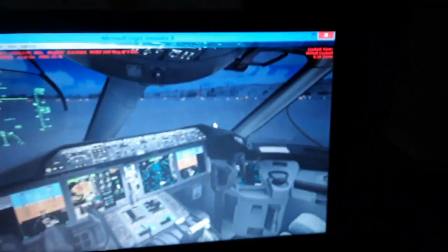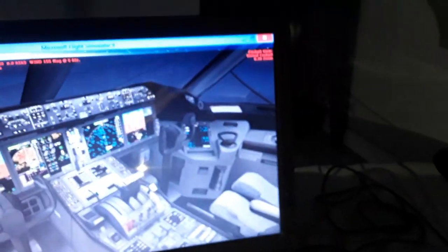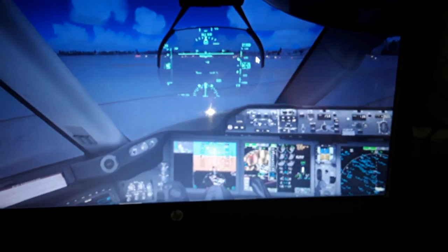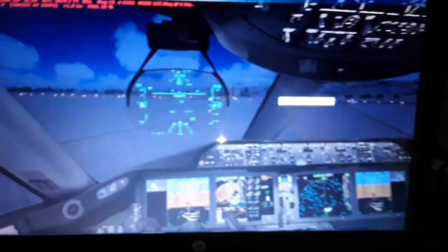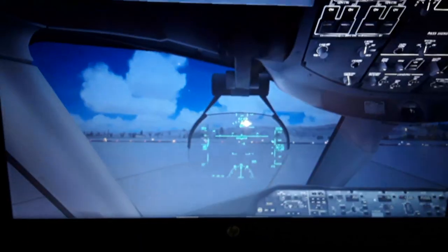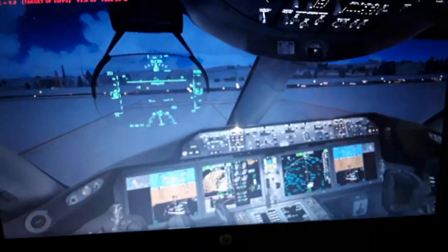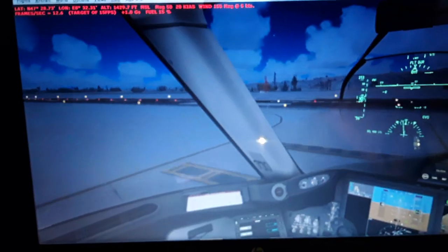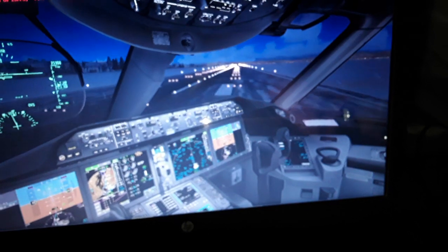Parking brakes off. We take the traffic control, the tower control clearance for takeoff. So we advance the thrust levers to takeoff position when we reach the runway. And to taxi first, so we use less power, and also we use the tiller for steering. So the air traffic control gives us the clearance. The runway is open for us. So we align here with the runway heading.